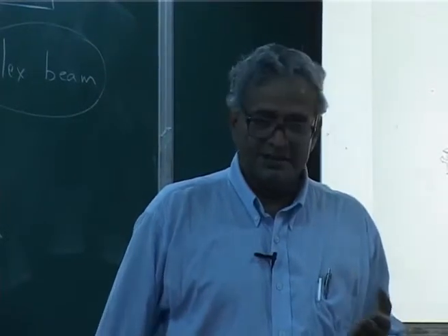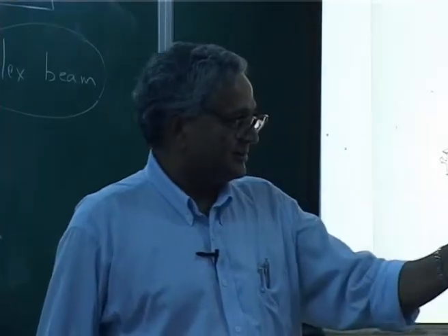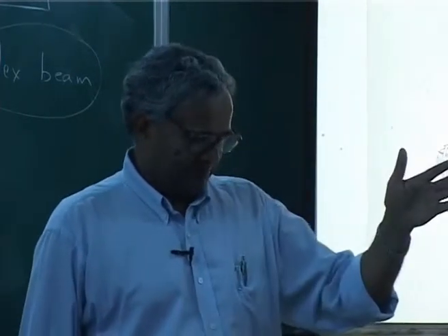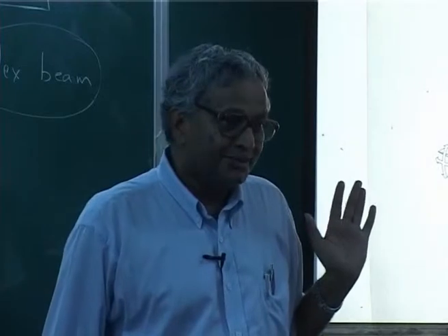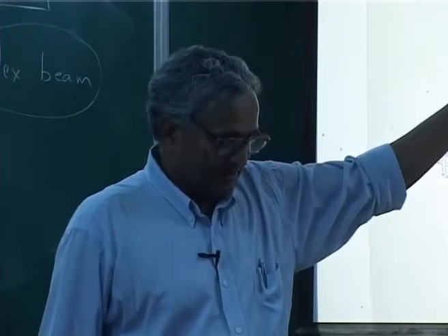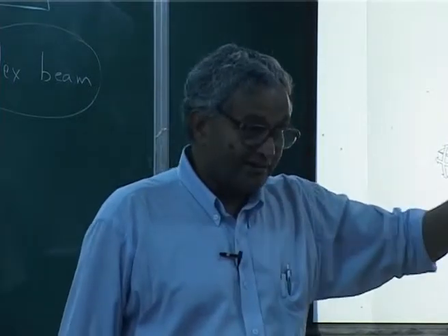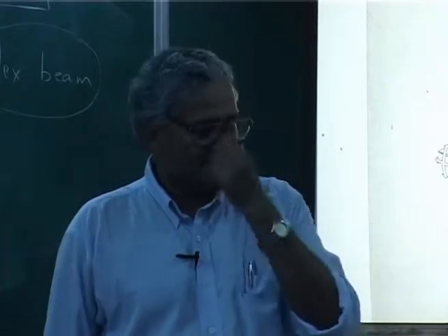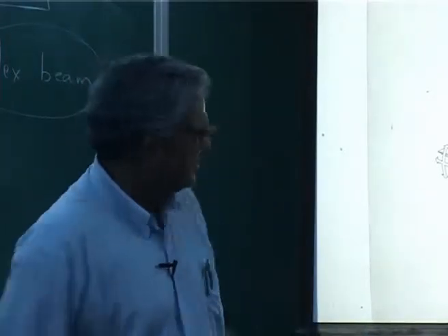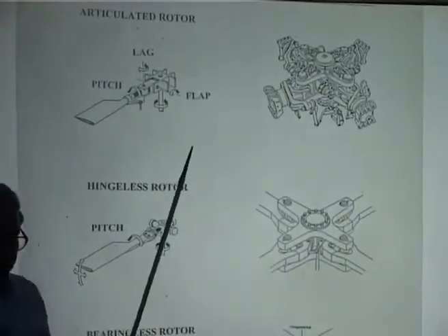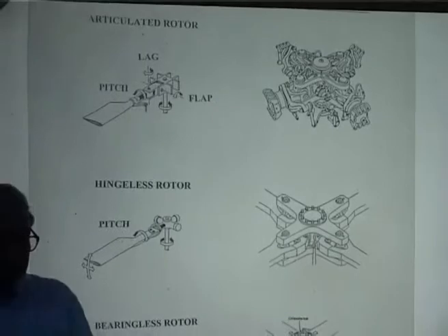The blade requirement is 5,000 hours of life. After that, throw it out. Every component may have some life. I was reading some material now, and that is a very interesting thing. The pitch link rod, the rod which goes from the blade to the hub, gets all the load.